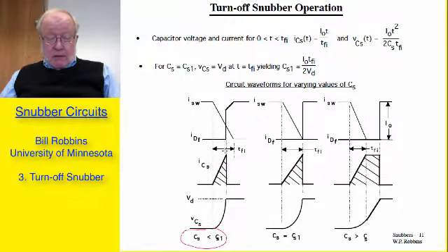The diode current then comes to the intermediate value that I'm indicating here, and then for the rest of the T sub FI interval increases until it reaches the value I0. The capacitor voltage is built up fairly quickly, and when it reaches the value V sub D, that's when the capacitor current goes back down to 0 and the diode current then jumps abruptly.